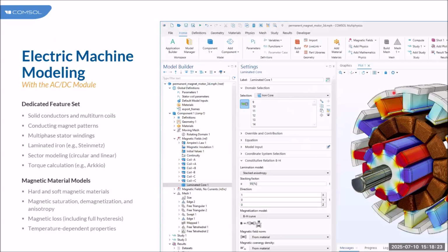So in terms of an electric motor, observe here, you can see a permanent magnet motor modeled in COMSOL. As you can see in this particular part here, these are the coils that will be wound on the stator, which is shown as an extruded version here for better visibility. We will be modeling the coils in COMSOL, and it can be modeled as a CAD geometry of coils. That is a general aspect, but mostly in motor cases, once we define the geometry of the coil or the motor,